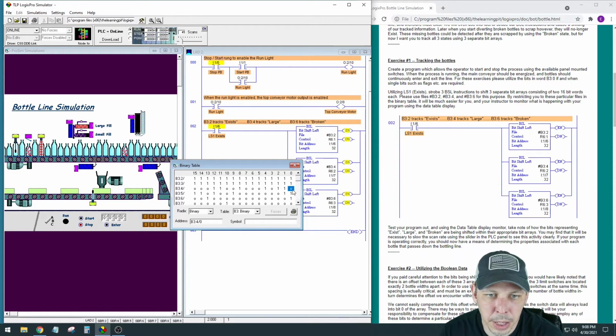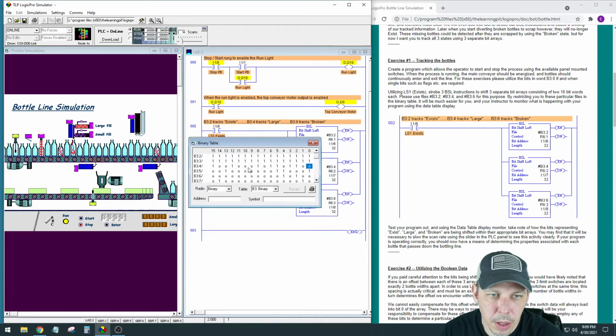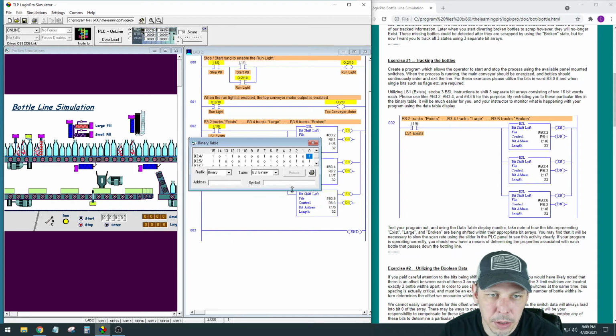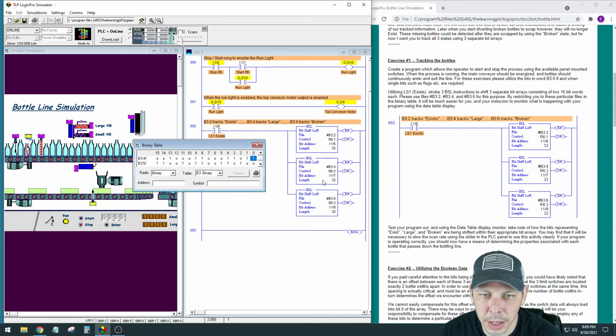And if we play it, you'll see that these are all just slowly jumping over to the left. Once they get here, they'll wrap around. So let me make it a little easier to concentrate on what we're actually looking at. So it starts on bit 0 here. So these group of 3 ones, you can see we can just follow it all the way across. And when it gets here, they start filtering in down here, and they're rolling across from right to left on the next 16-bit word right underneath it, because we set our length as 32 bits.